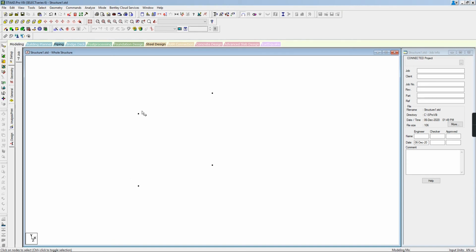Okay, now I would be connecting these nodes. I use my add beam cursor. So this add beam is for connection between two nodes, right? I will be adding beam like this. So this is another method by which I can generate my model by using Control C and Control V. Okay, so now our model is complete.